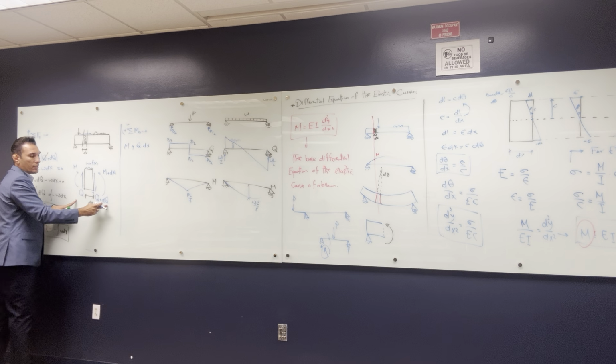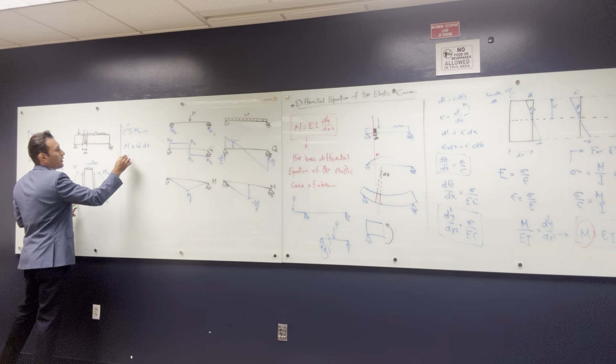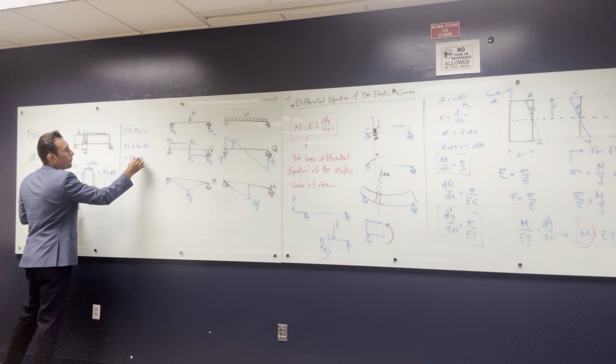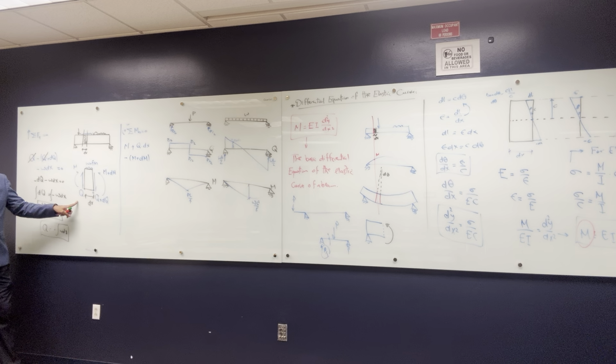How about Q plus dQ? How much moment does it do? 0, because it passes through O. All right. How about this one? This one is going to be minus M plus dM. Do I have any other loads that make moment on this section? W. The W, right?